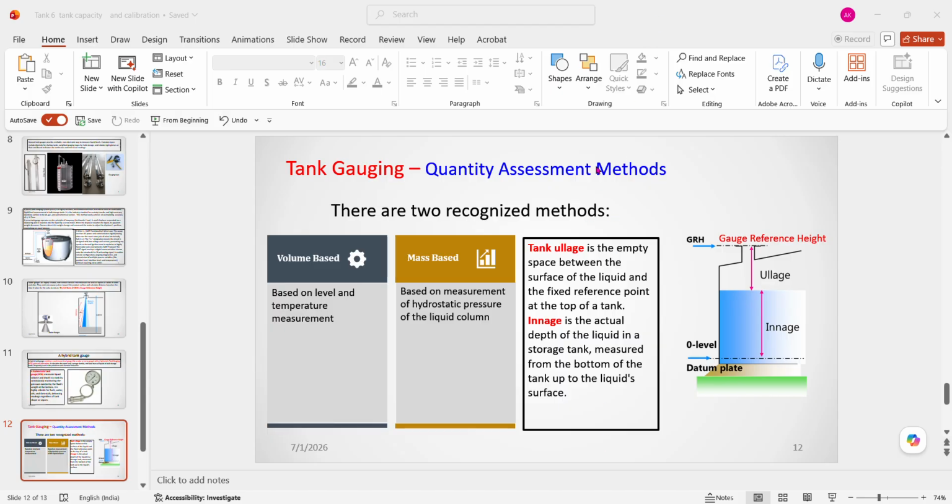When microwaves travel, they strike the level or fluid and then bounce back. The time taken going down and coming back, with the velocity and divided by the time, will give you the length, and that will give you the full level of this tank.